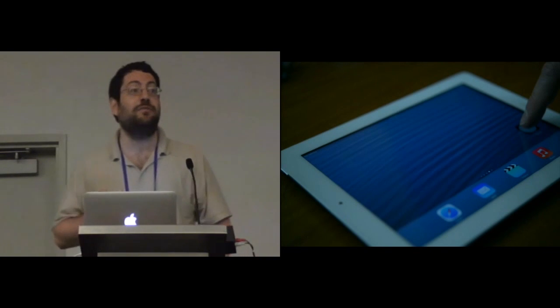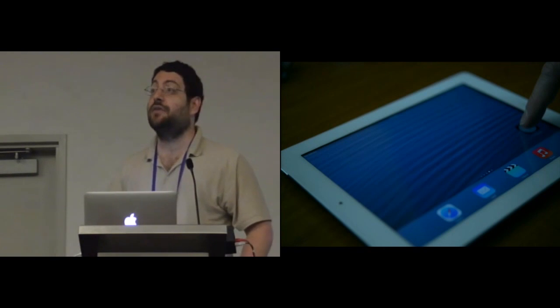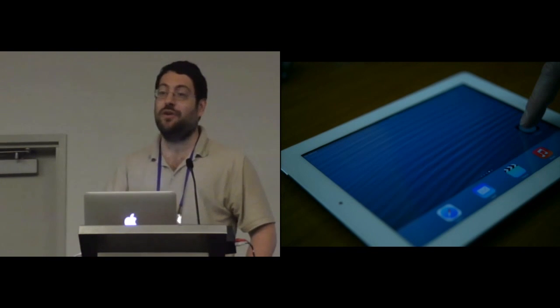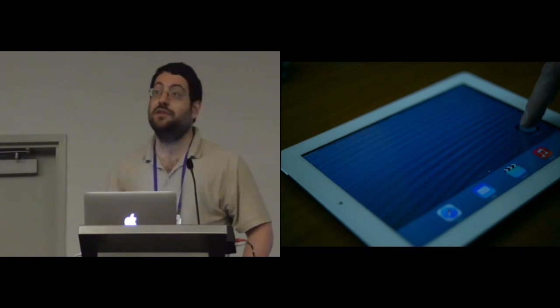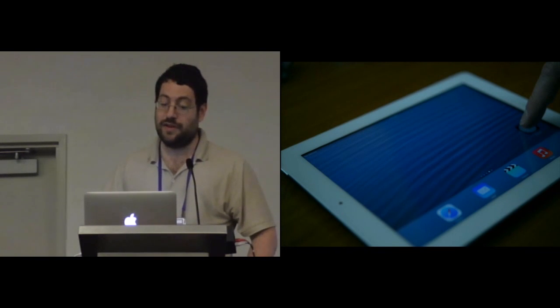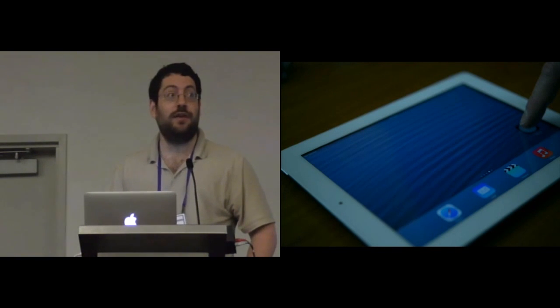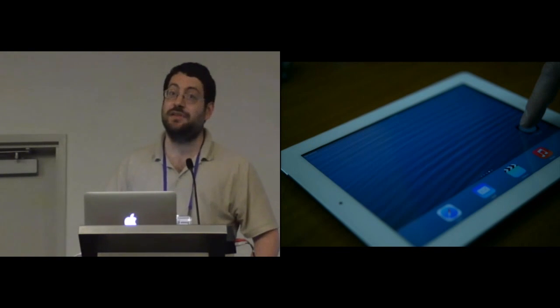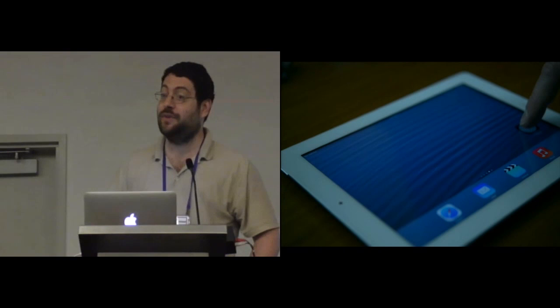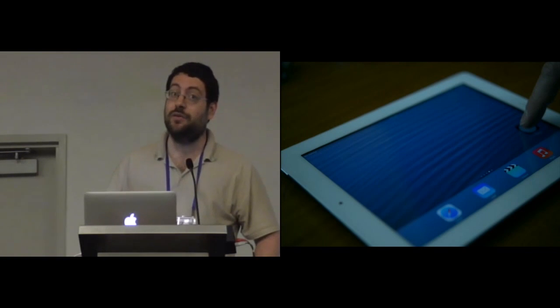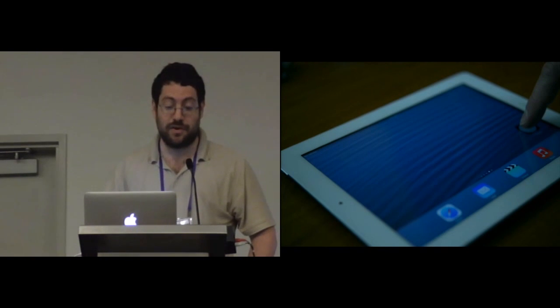You have sensors that have to be read. You have many layers of software that have to process it, ranging from the driver all the way up to the application level. And you finally have to wait for the display to update. And despite the march of Moore's law, there's still noticeable latency in all commercial devices. At best, the time difference between a tap and a response to the tap is down to about 33 milliseconds. In many cases, it's much, much higher, as high as 200. And humans can perceive down to 5. So it's clear we still have a ways to go to remove this impact on the user experience.